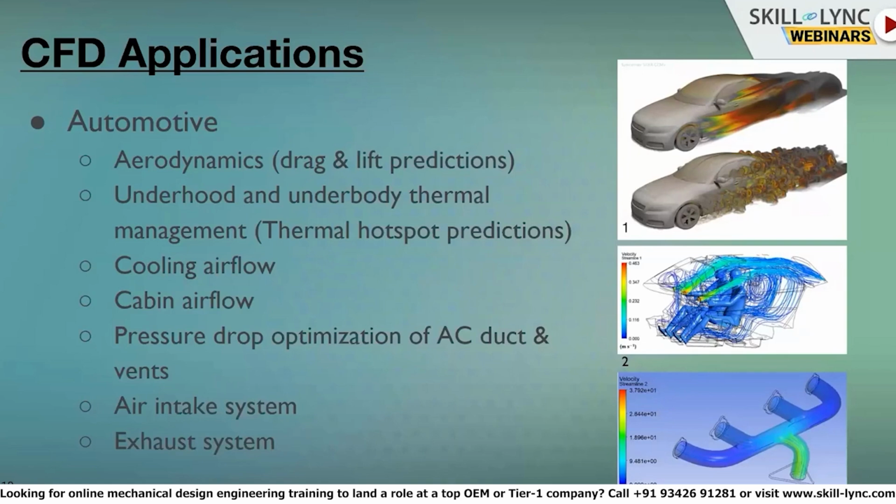Another is cooling airflow. You all might have seen certain openings on the front of the car. Those openings are provided to cool the heat rejected by the engine through the radiator into the engine bay. That heat will be carried out by this airflow. So one may have to work on optimizing the airflow requirements based on the heat rejection.